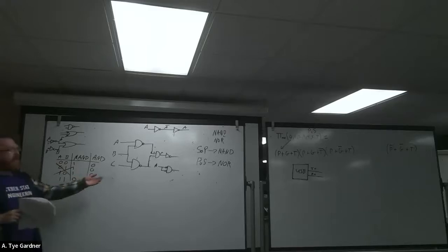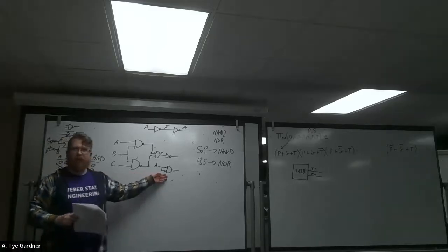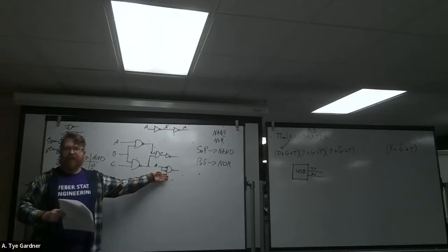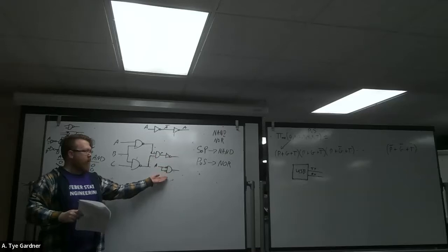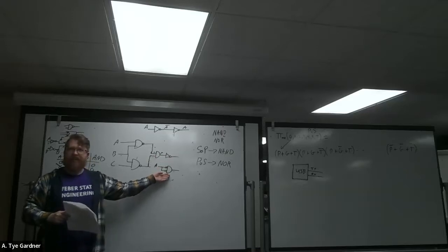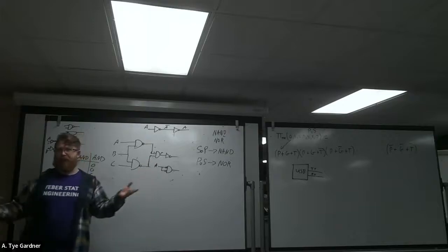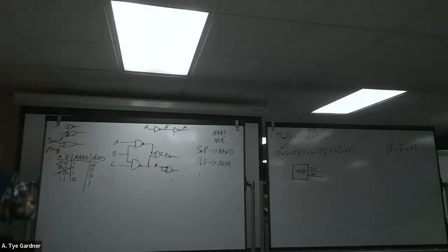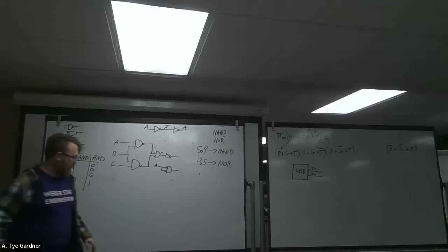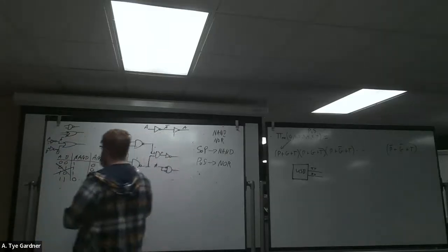So as a matter of practice and protocol, if I ask you to design this circuit using universal gates and you just draw an inverter, you don't have to draw this NAND because it's really easy to make inverters out of NAND gates. The same is true for NOR. It's probably going to be a homework question, but the proof is easy. It's just truth tables. Okay, sorry, I had to double back on that one, but I can start pushing forward to the next topic.